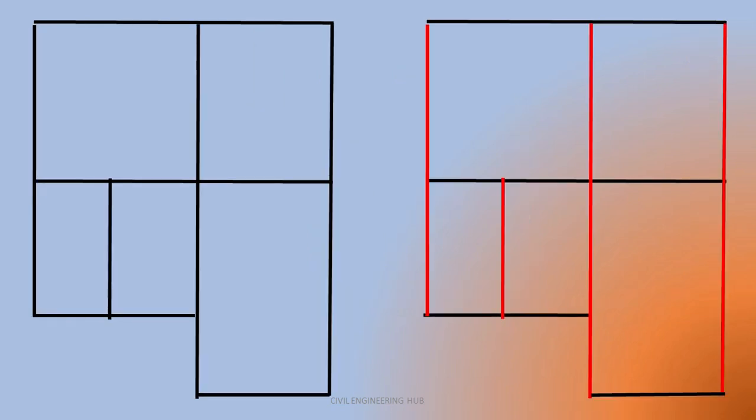So this is a one line plan for this map. Here we are neglecting the door and window position. In the entire structure we are considering walls for ease of calculations. In this particular plan, I have divided the horizontal wall as a long wall, and in the second plan I have divided the vertical wall as a long wall.